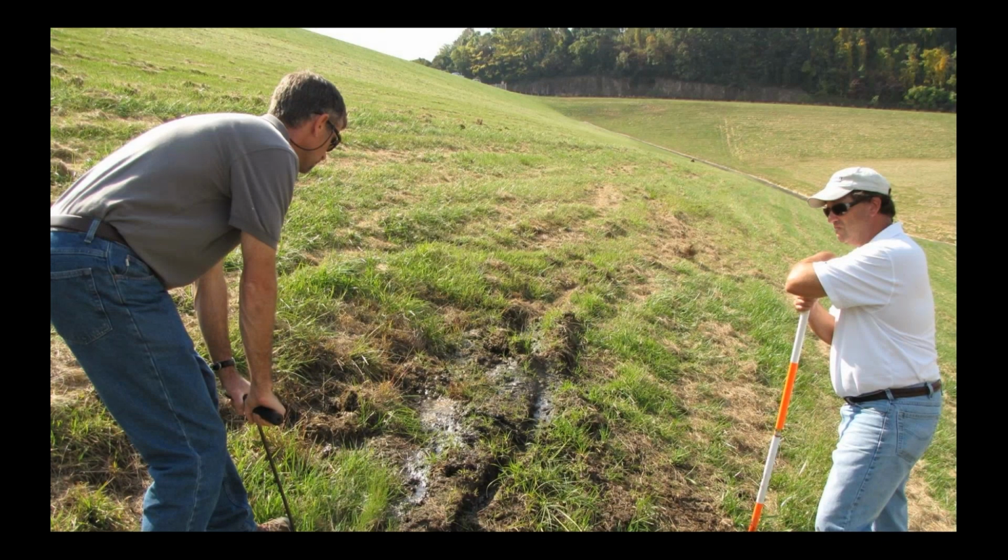And as you're inspecting it, you're looking for any areas where you could have a high phreatic level that's daylighting through the downstream slope of the dam. And that could happen if you don't have good internal seepage collection and filtering. It could also happen if there's a defect in your filtering system. This particular dam was modified in the 1980s, and they used a geotextile instead of a sand filter. And it worked for a while, but eventually that geotextile became clogged, and then it just became ineffective.